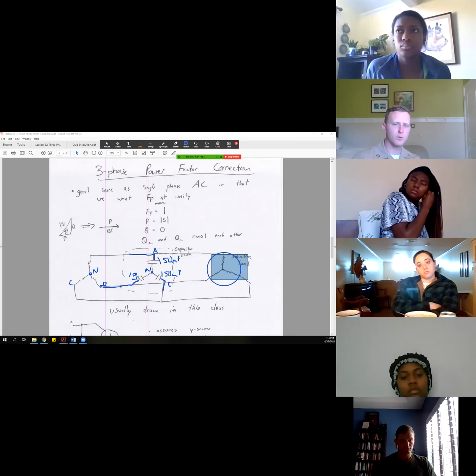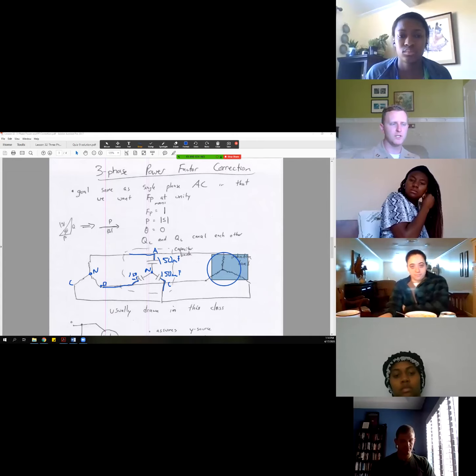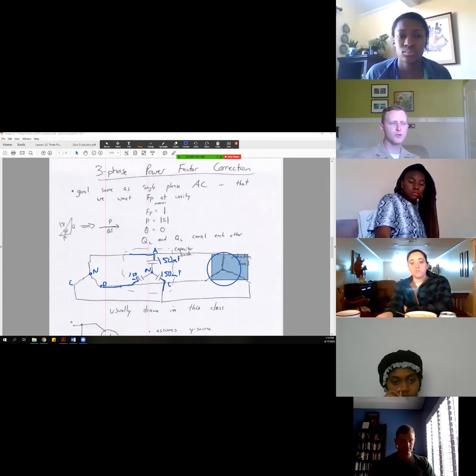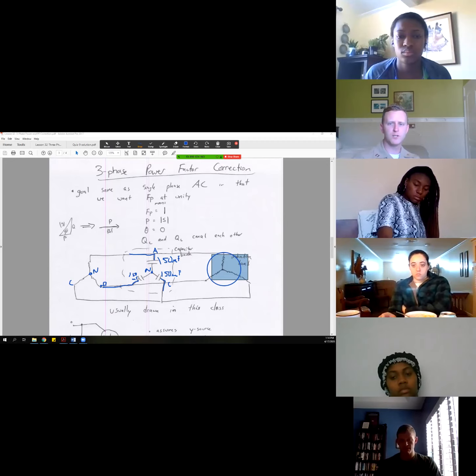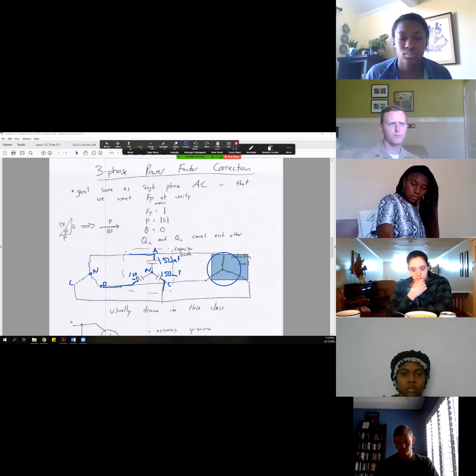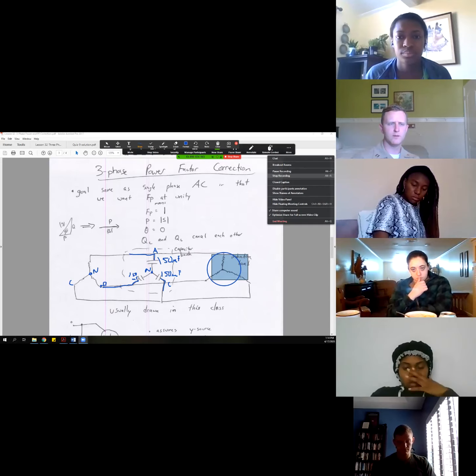And that's why this single phase equivalent is so powerful. Going from a 3-phase, what was complex, to this idea of a single phase makes it much easier to solve. That's also why whenever you're using the equation for Q, you're going to use V squared over X, and the V that you use is just the individual VAN or EAN. Okay, I think that is enough.